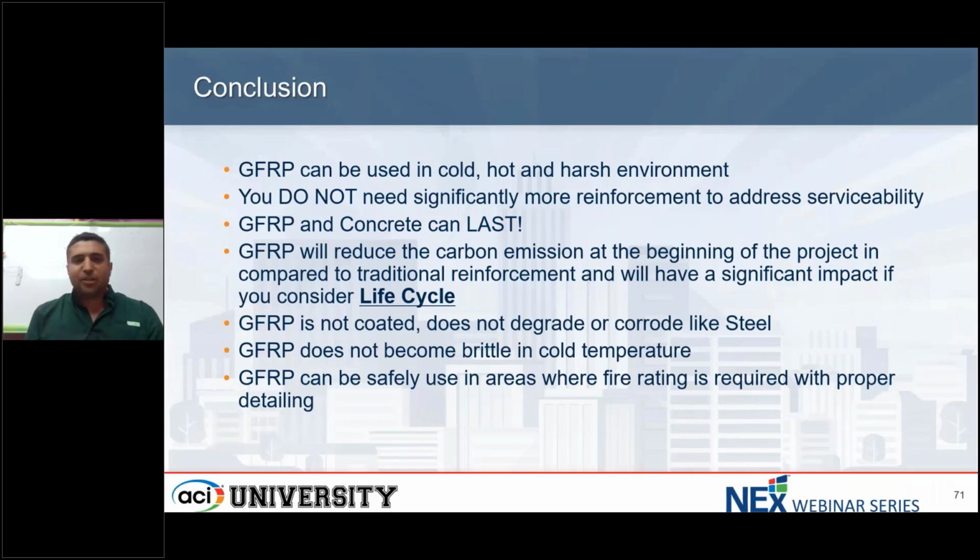That's pretty much it. On the conclusion side, we can emphasize that GFRP can be used in extreme cold, fire, and harsh environments. You definitely do not need significantly more reinforcement to add serviceability, as we talked about. GFRP and concrete really can last long together, and it's time for the industry to take advantage of this good marriage made in heaven between concrete and GFRP.